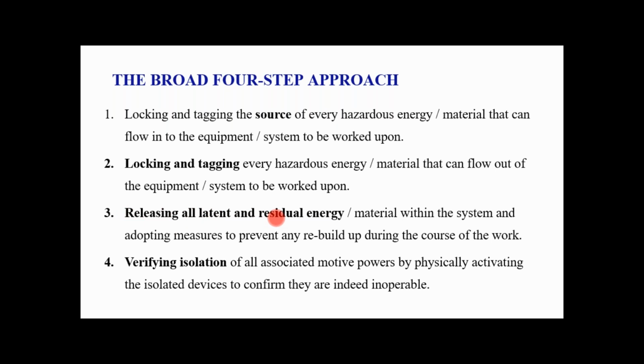In the case of other types of energy, these are the residual energy. Suppose there is a chemical which can react with matter, with oxygen, or with water itself. So the residual part of that particular chemical may act as a residual energy. So we have to drain out, clean that equipment, and remove that chemical or material from that source. That is the third step.